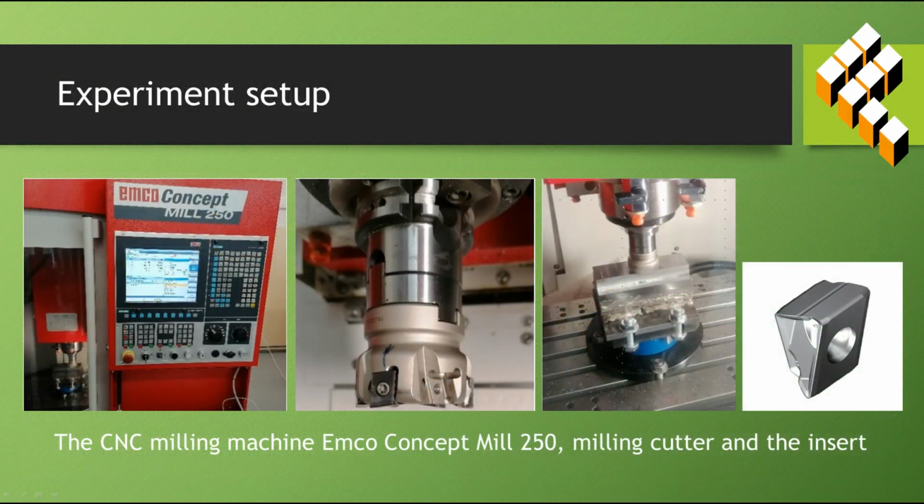We planned and conducted a factorial experiment of high-speed face milling of a workpiece from hard-to-process steel, which is used for the production of ship hull structures. We determined the depth of cut, the speed of the main cutting movement, and the speed of the forming movement, the feed rate, as the influencing factors. The cutting force components have been measured for each experiment.